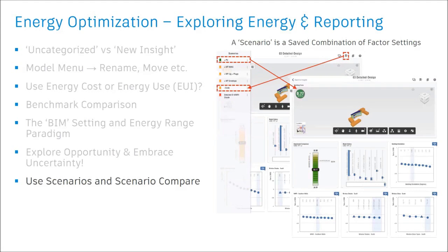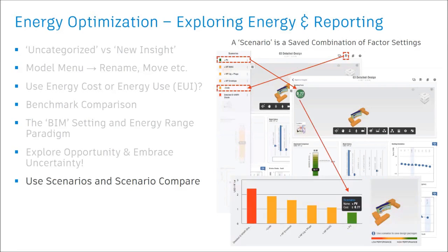So again, a single model that I've generated, run in the cloud, and because I can move factors around, I can represent it. Like I said, I don't have to go back to the Revit model and have everything embedded in the Revit model. I can just do that as an optional step of documentation if I want at a later stage. But the cool thing about this is that if I create these different scenarios like I have here, from essentially doing nothing, to improving the envelope, reducing internal loads, then high performance HVAC, and then adding on some PV, you can see very quickly within Insight, just compare. So this is a step down, all the way down to hitting Architecture 2030 total building cost.